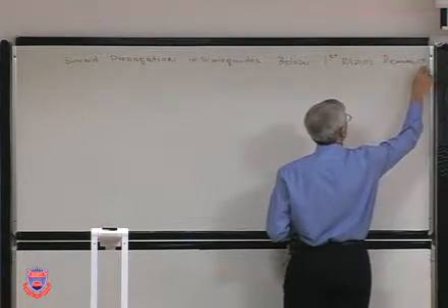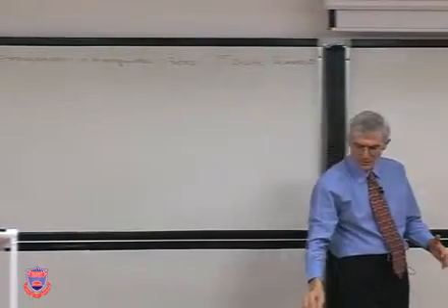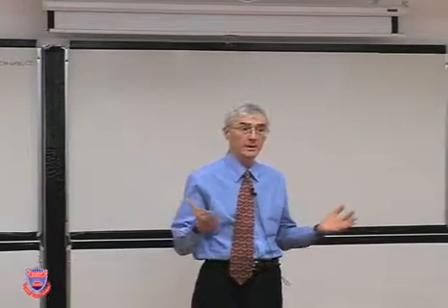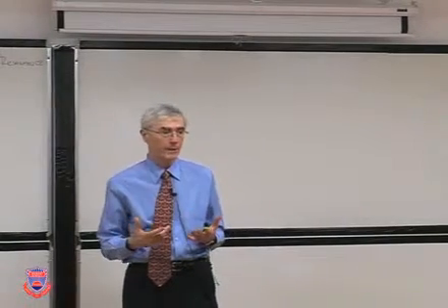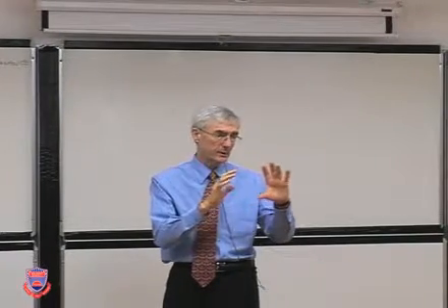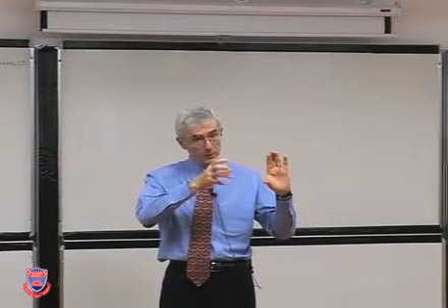By the way, we have only used these rectangular coordinates, the Cartesian coordinates. What do you think would happen if there's a circular duct? A lot of pipes are circular. Water pipes, they transmit sound. What do you think will happen? Changes the wave equation, but the same physical phenomena will also take place, except that it's not x and y, it will be in the radial direction and also torsional direction.